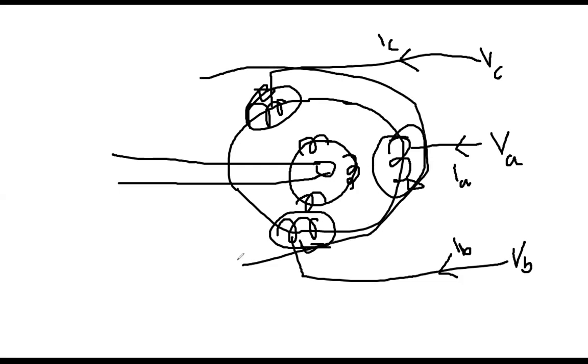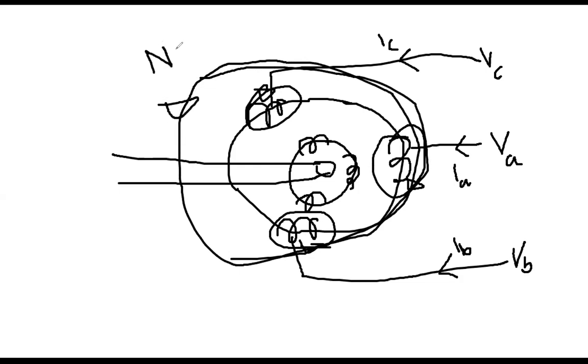they are really rotating. They are moving. And that rotation speed is exactly the same equation, N synchronous equals 120 F over P. So everybody, this speed is not the shaft speed. This speed is called the synchronous speed. But everybody, this speed is the rotating magnetic field speed. This is not the speed of the shaft. Still the shaft has not rotated. Everybody keep in mind, don't mix up. This is the synchronous speed of the rotating magnetic field, which was built up because of the application of the voltage.